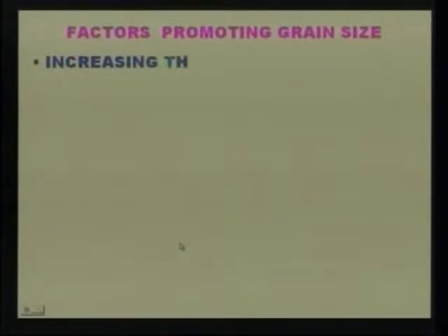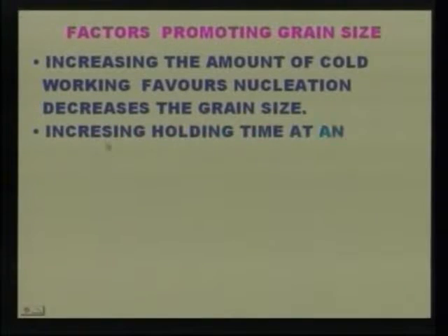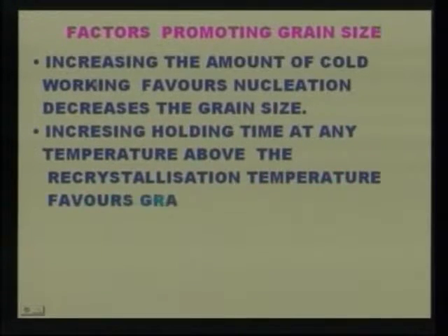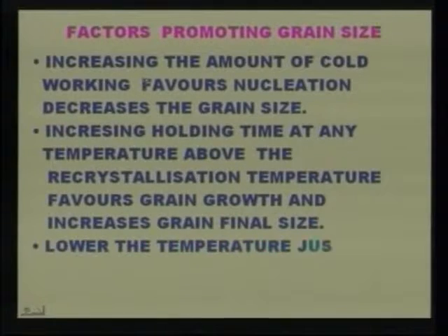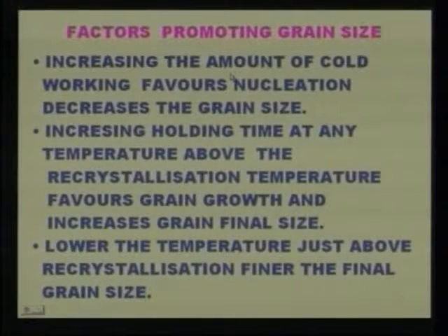Now let us see the factors that control grain size. Increasing the amount of cold working favors nucleation and decreases the grain size. So by increasing nucleation, we increase the number of crystals formed, which promotes a fine grain size and decreases the size of the grain.